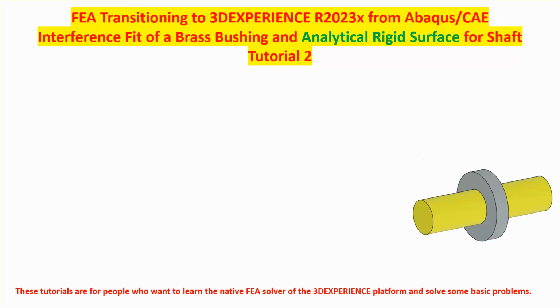Hello folks, this is the second video tutorial that I'm doing for solving some very simple problems in the 3D Experience which involve contact. I want to remind you that the solver in the 3D Experience, FEA solver, is actually the Abaqus program. And the first tutorial dealt with the shrink fit problem, as shown here on the right hand side below, where there is a brass bushing that is shrink fitted onto a shaft. I assumed in the first video that this shaft is actually rigid.